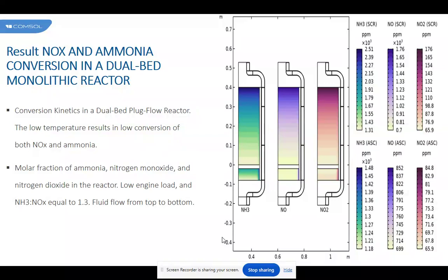The temperature differences along the reactor axis at the center of the reactor and at the edge of the beds are seen here in this simulation. Close to the inlet of the first bed, the temperature increases both at the center and along the SCR edge. This is due to the exothermic reactions. After the first rapid temperature increase, the increase in the temperature is slower, and at the edge of the first bed, the temperature instead decreases due to the heat flux to the surroundings.